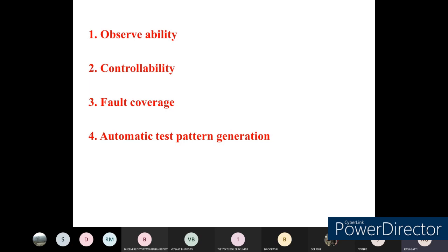And then what we do is the circuit is simulated with test vectors, comparing the chip output with a known functional machine. So we are going to use a finite state machine, which is known to the designer. With the use of the known functional finite state machine, we are going to simulate the circuits by using different test vectors based upon the finite state machine.